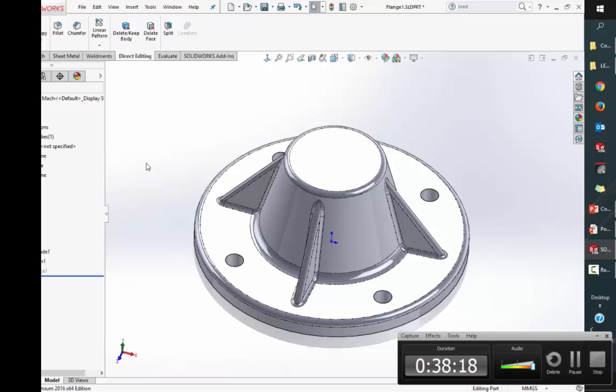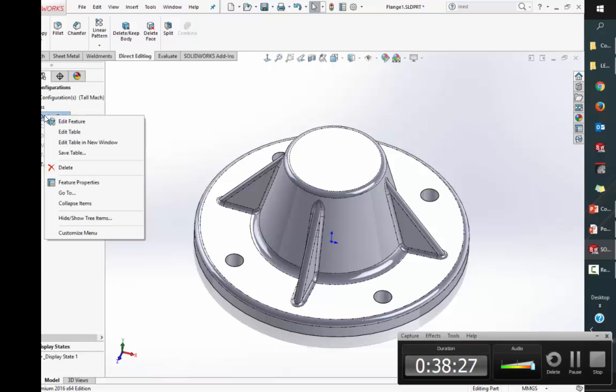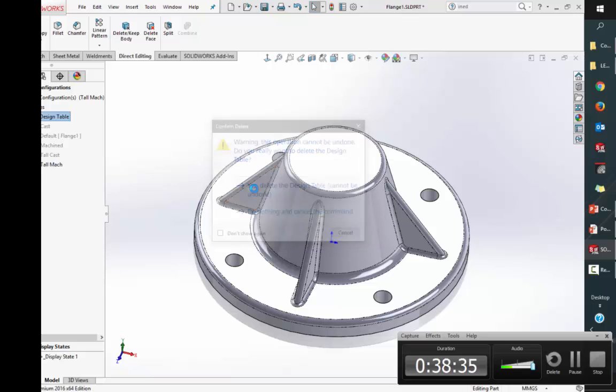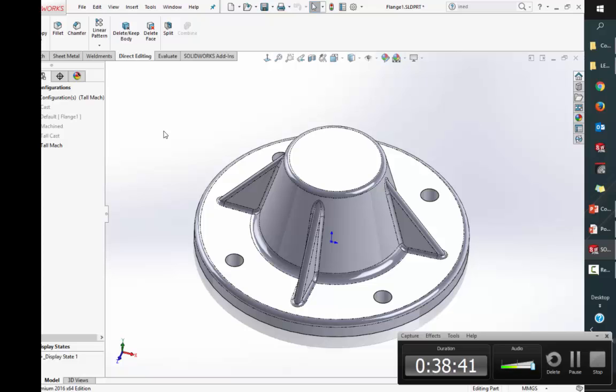Yeah. So, delete it out of your table. Delete the table. In fact, sometimes you just want to do that. The fact of the matter is the Excel table is actually stored within the file, which can cause corruptions periodically. And so you'll call up your tech support person, and they will say, "Oh, it's easy to fix. Just delete your design table." And you're like, "Ooh." All right, it's not too bad actually.